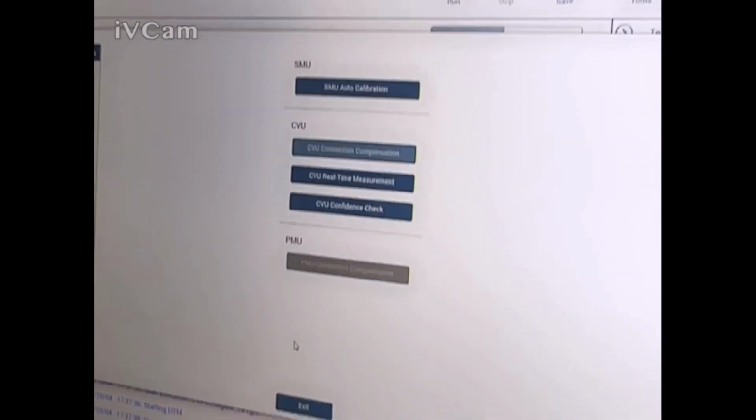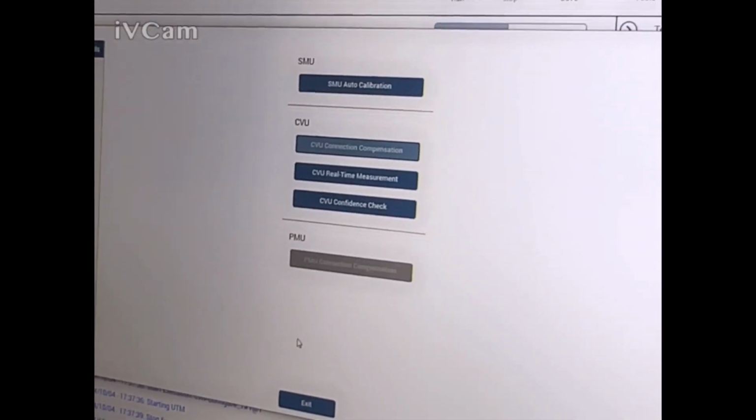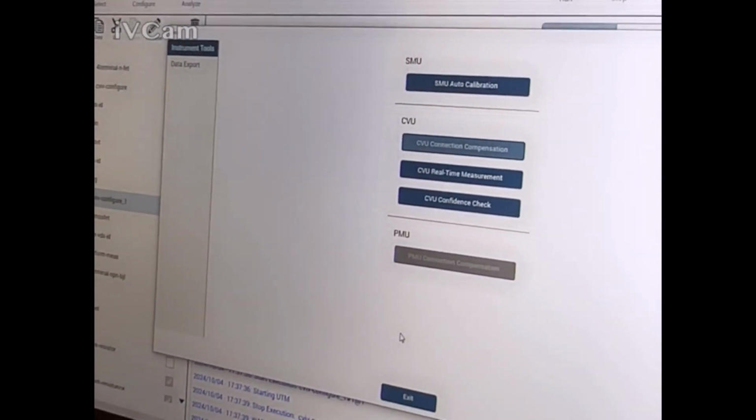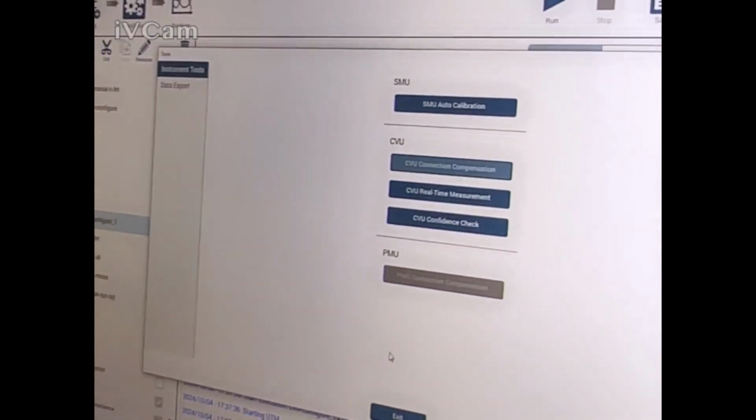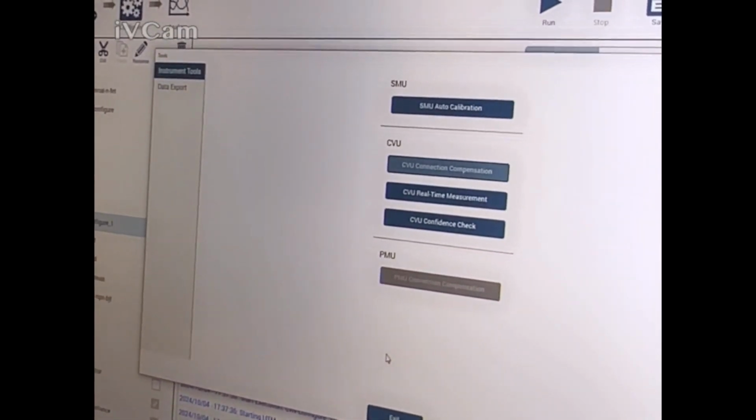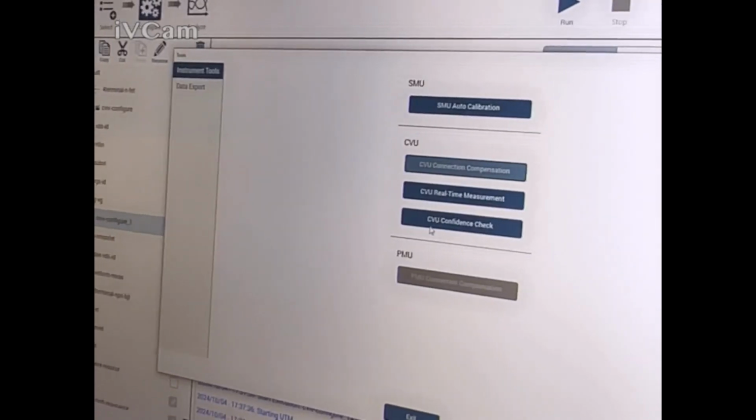And then it's going to run through. On the probe station, you just don't connect it and you don't put the device, so you drop your chuck. Right? So that all the cabling is there, your fixturing, cabling, everything's there, but not the device. Right? Because that's what you're trying to get out. You're trying to get all that cabling and all that capacitance gone.